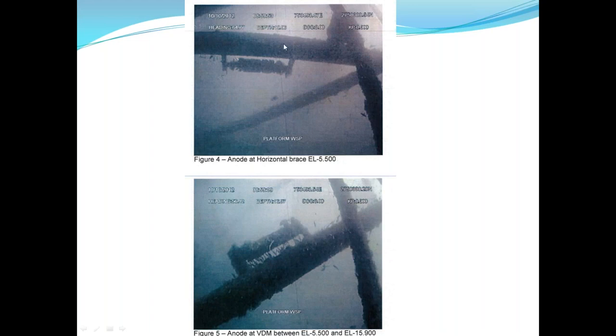And whatever you are seeing is all marine growth, that means algae formation. Every 5 years a diver will go inside the ocean and clean all the algae, because whenever this algae increases, the diameter increases. Whenever diameter increases, the structure will absorb more waves. That is not good for the structure because it will create more base shear and more overturning moment. It is bad for the pile foundation. So in order to avoid all those things, a diver will go down until the seabed and clean everything. And remember that diver is highly paid.